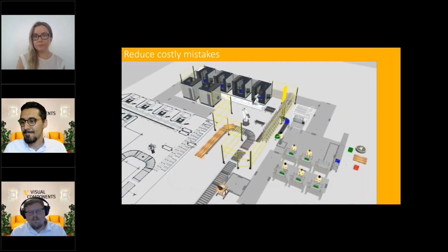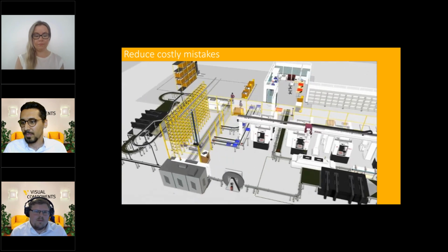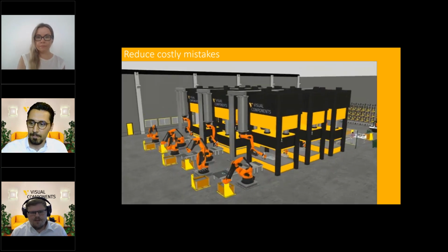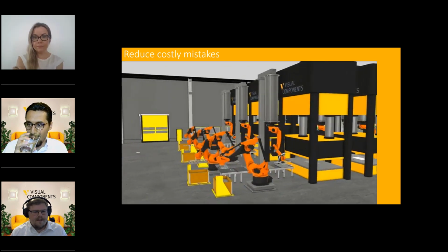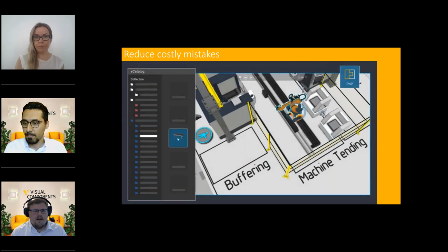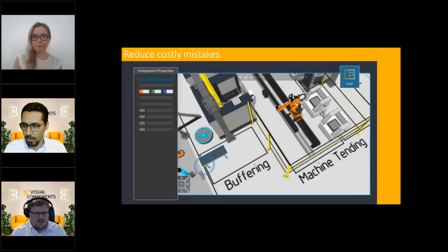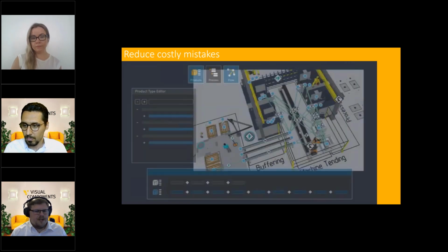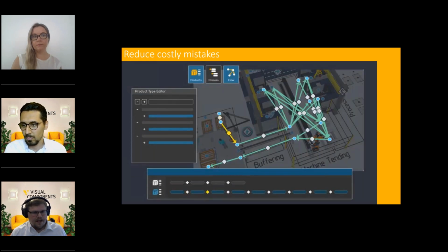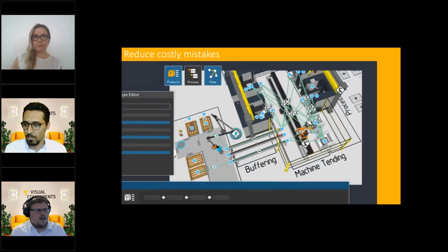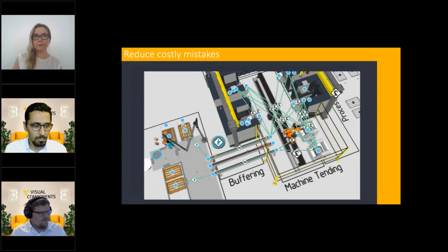Good question, Reza. So basically, if we talk more about our software, the Visual Components platform, we have this large library of components. And in the library, by default, you will find over 70 different grippers. So you could simply try with another one and see what happens. Do I get now the reach that I need? Does it change the reach in the direction that I need it? Yes or no? If no, okay, let's try another one. And we can kind of narrow the problem down towards a solution that would fit our requirements.